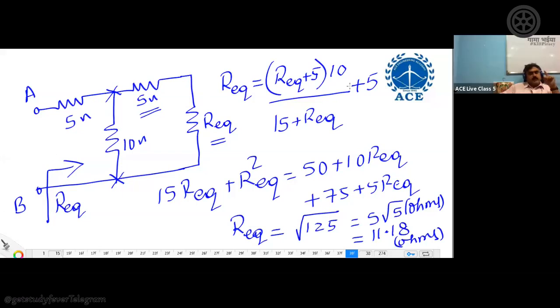See, when you are drawing the network in steady state, it means after settling time, once your TS starts. At that point of time, this current source which you are representing is actually the stored value of the current on the inductor. It is not actually a current source. We are representing it as a current source, but it is actually the stored value of the current. So that current will be dissipated on the remaining elements present in the network.